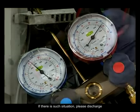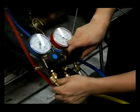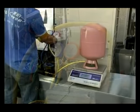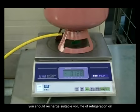If there is such a situation, please discharge all the refrigerant of the system and vacuum again. Recharge the refrigerant after it has reached vacuum requirement. If refrigeration oil goes out during the process, you should recharge suitable volume of refrigeration oil.